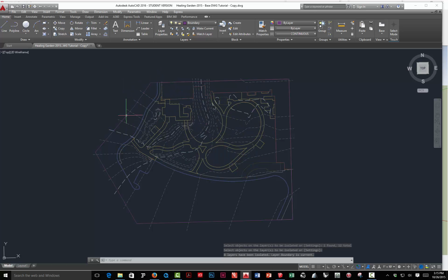I've got the boundary, and again, this is a boundary that I put in AutoCAD to give me an edge for the site model in SketchUp and an edge for the 2D surfaces that we're going to create first. It's not part of the original drawings, but I needed it in order to create that boundary. And you'll see how that works in a little bit. All right, so I've flattened everything with the contours. I've exploded all the polylines, so I make sure I have arcs. And now I'm ready to use the W block command.